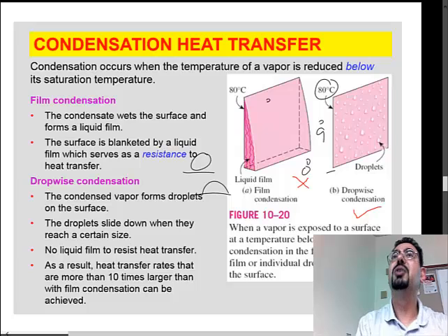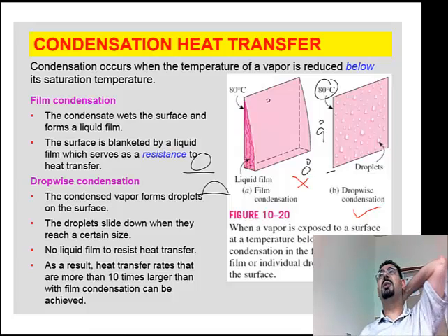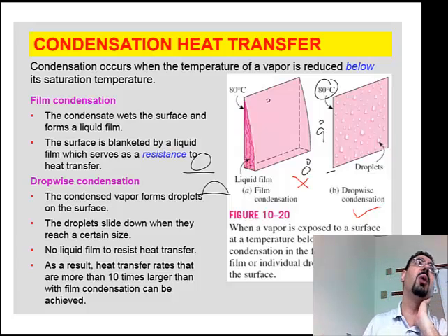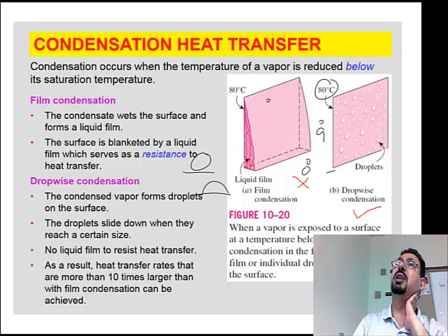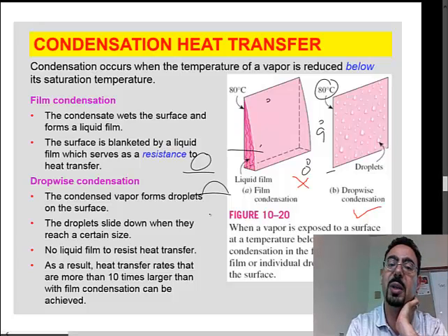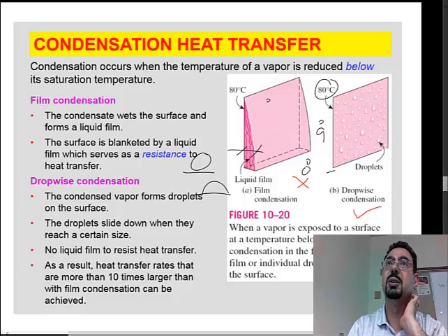Alright? So eventually, of course, this treatment doesn't last, because that wax layer or whatever they are using will deteriorate after a while. And the surface goes back to its original nature, and then they lose this dropwise condensation and become film condensation again. Alright? But think of this film as nothing really helping you.